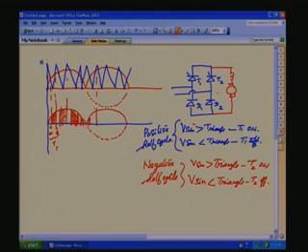Sine greater than the triangle, so here T2 will be turning on, and T2 will be turned off at this point. So, this type of pulsed waveform is coming across the output load. Previously, the full part of the mains waveform was coming here. Here is a pulsed part. Now, the average value depends on the area, total area divided by the period. Here the period is 1 by pi. So, as I told before, with this pulse waveform we can have the same output DC voltage.